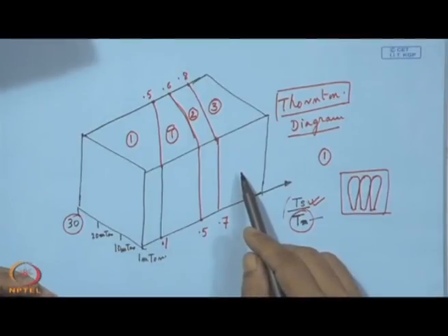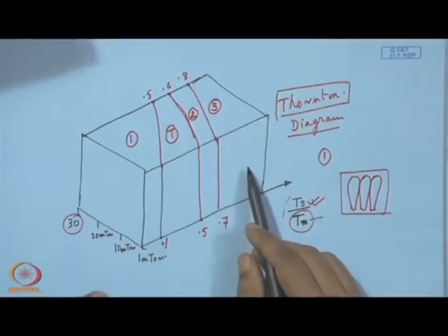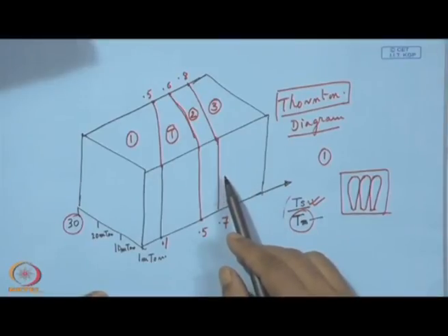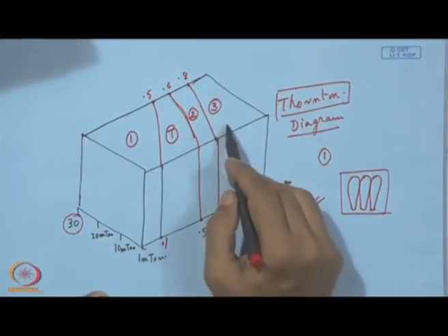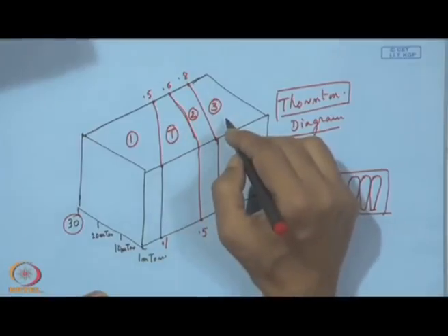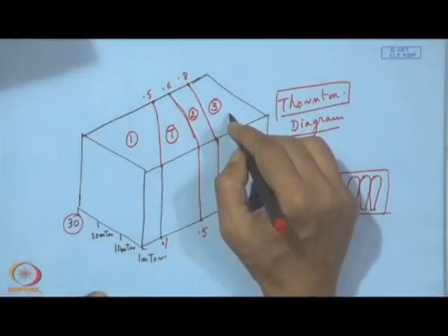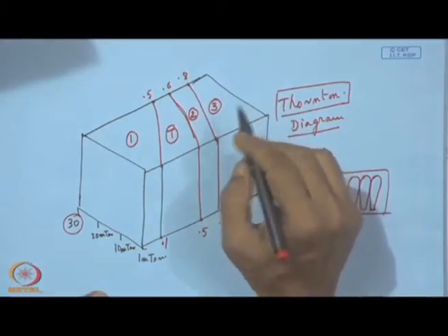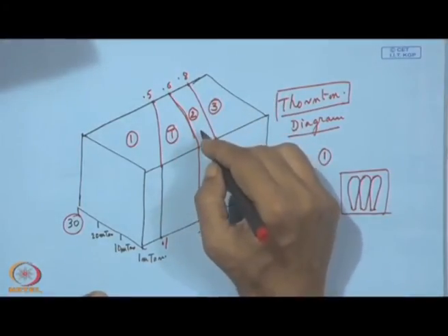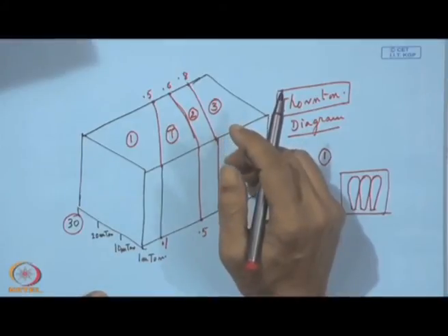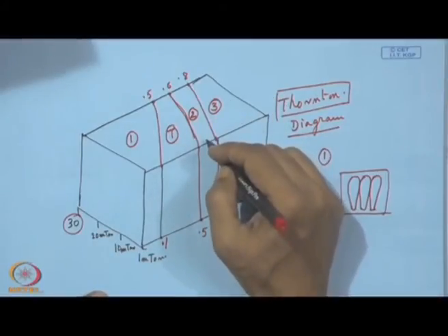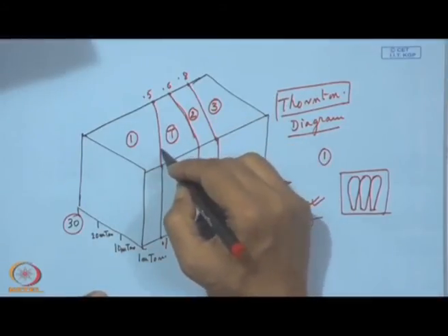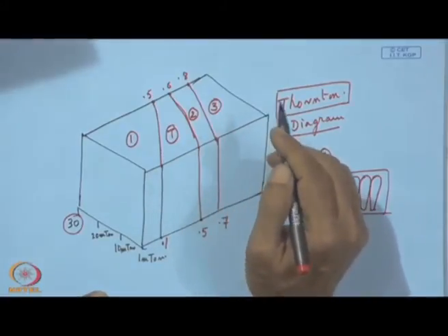So, it is actually this mobility of these adatoms and the lateral movement that makes a structure which we call equiaxed. It is very grainy, a grain-like structure in zone 3, and zone 2 is a highly packed broomstick, a very dense structure, and it is a transition that is changing.